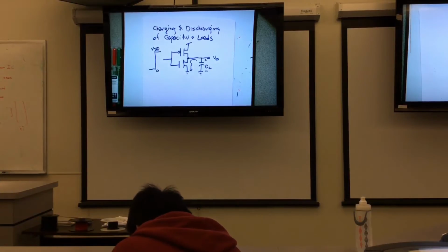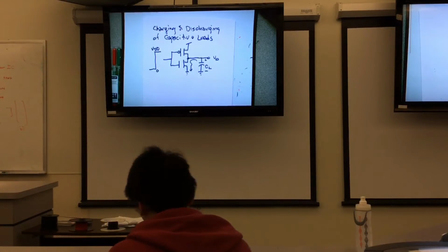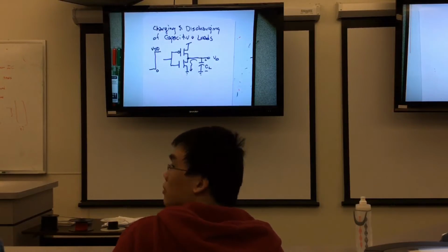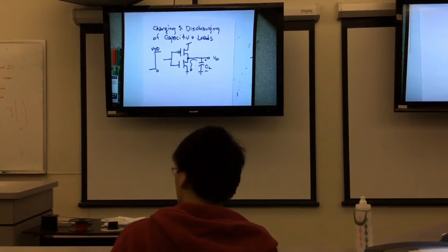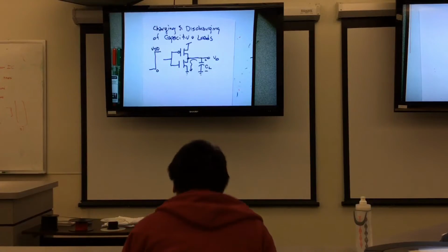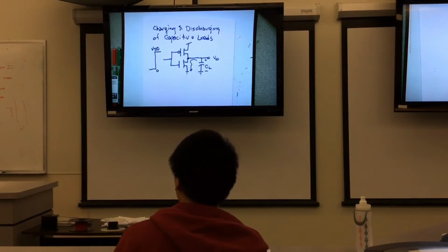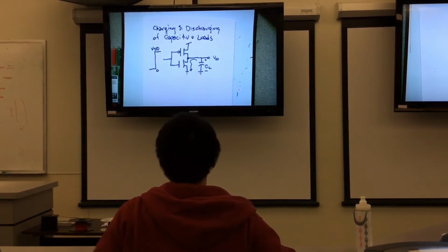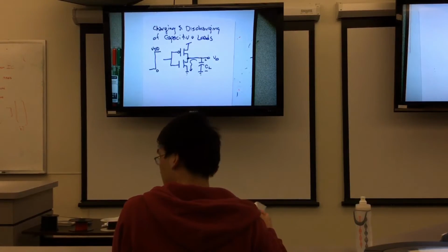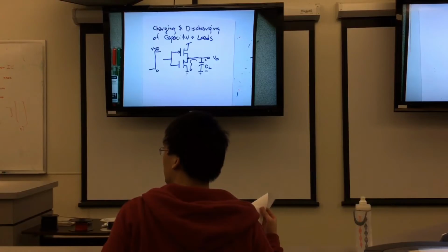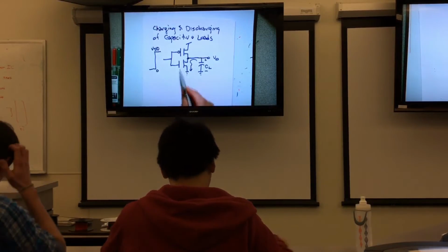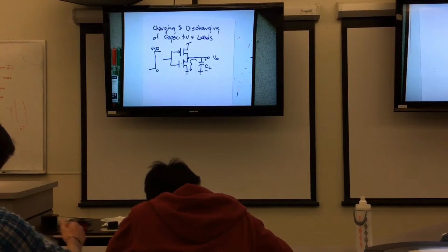Incidentally, this is where a lot of energy disappears. People like CMOS because they think it's low energy. But what we're doing is dealing with tidal flows of energy in the form of charge storage, down to this conductor. And then we dump it to ground. And guess what? When we do that, the charge produces zero voltage, and the energy has to go someplace. Where do you think the energy goes? Heat. In the transistor.